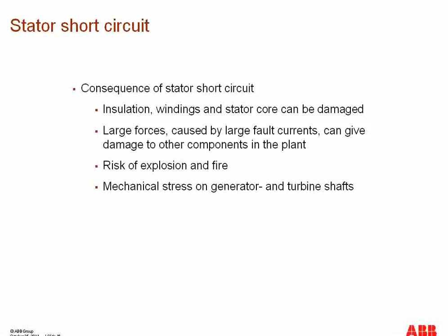Also, there can be extremely large mechanical forces and stresses and torsion variations, which can actually destroy the turbine shafts as well as the turbine blades. So we have to protect against phase-to-phase faults also.